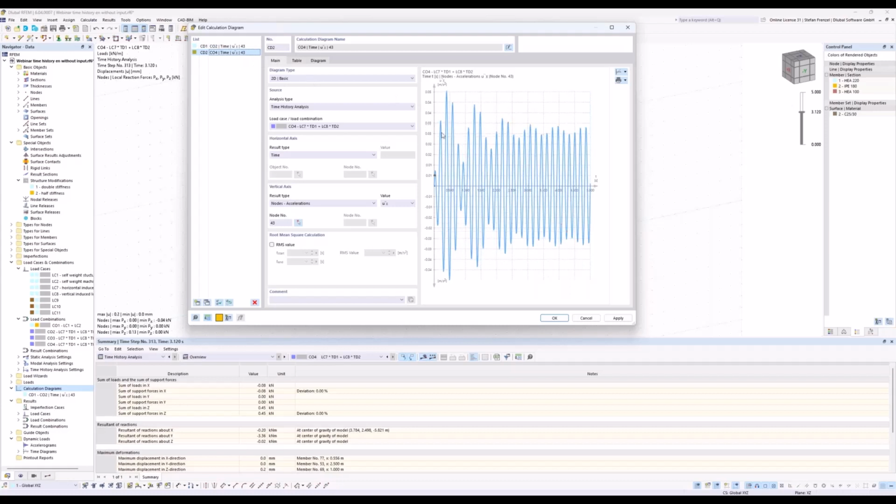And therefore you can choose a smaller or a bigger cross section. That depends on you and maybe also on the stress level of the structure. But normally these bracings could be really small, because you just have normal forces in them, since they are hinged at the start and at the end. Therefore it is normally not necessary to use big cross sections.